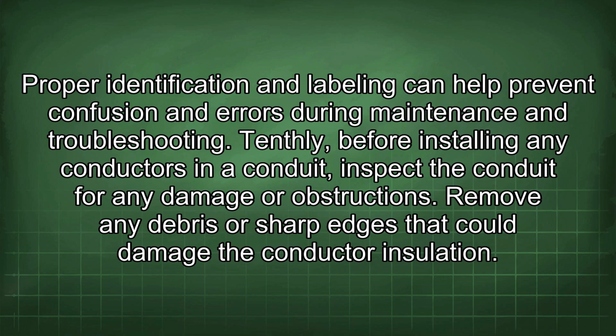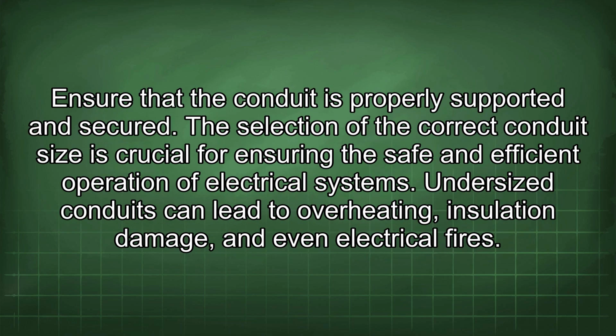Tenthly, before installing any conductors in a conduit, inspect the conduit for any damage or obstructions. Remove any debris or sharp edges that could damage the conductor insulation. Ensure that the conduit is properly supported and secured.